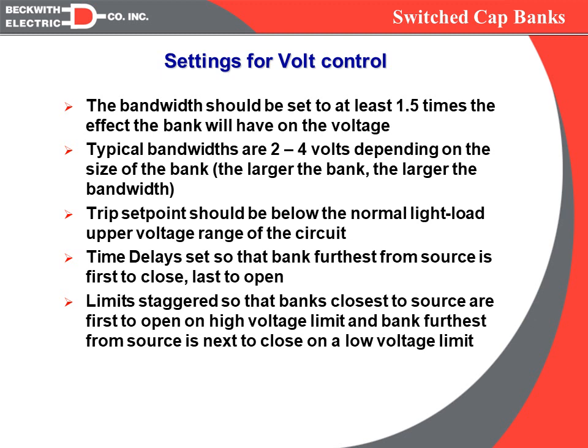We also want to set limits on the cap banks, and we want to make sure that any emergency voltage limits are set such that we keep that same coordination. So again, if I've got a low voltage limit that's going to want a cap bank to close, I want the cap bank furthest to be the first to close. And I don't want them all to close at the same time on a limit, because then I can get into a hunting where I go the opposite direction.